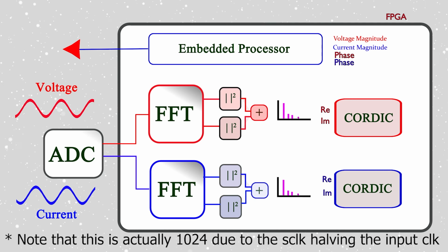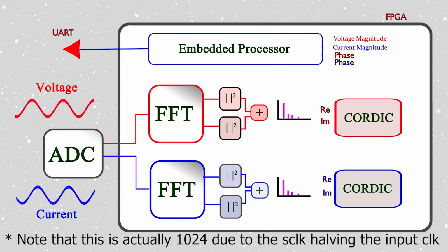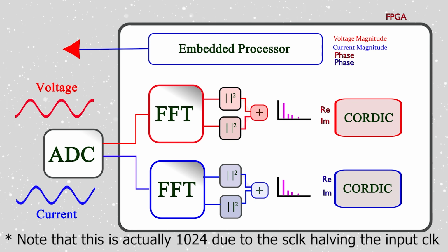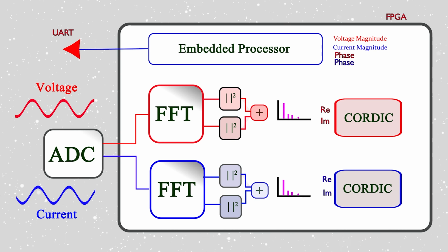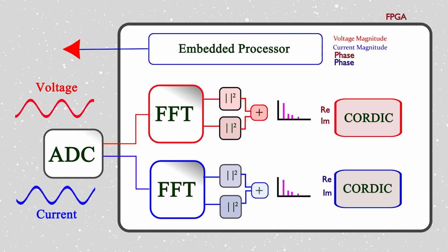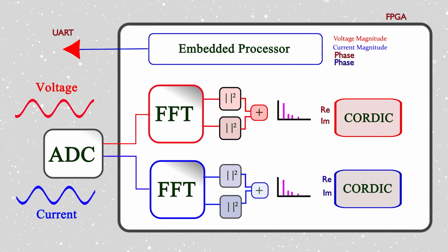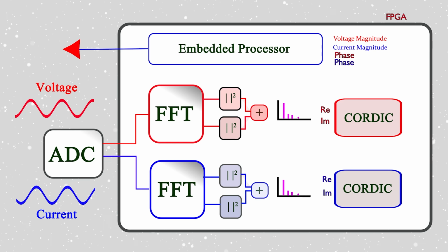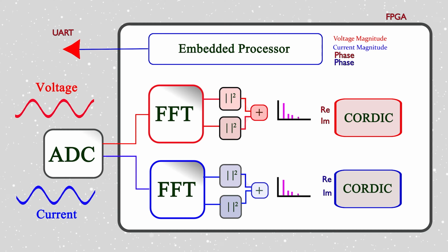So what I'm also doing in the A to D converter code is producing a much slower clock, which is feeding the FFT, and that will sample once every new data sample emerges from the A to D converter.